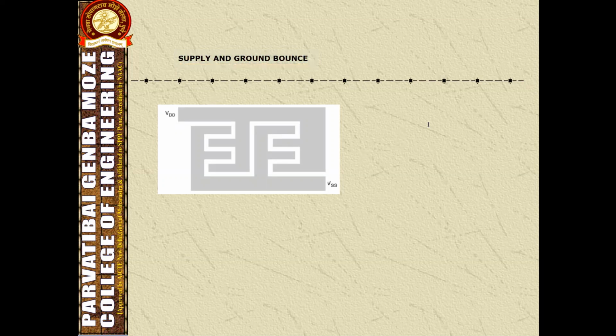The output voltage of an IC is with respect to the ground of the chip. Hence, in a system, the tiny wire connection between the chip and the lead frame of the package contributes a small amount of inductance in a circuit. When Vout goes low, a spike of current flows through this inductance and creates a voltage spike. A device connected to the ground of the circuit indicates a logical zero. This is called a ground bounce.